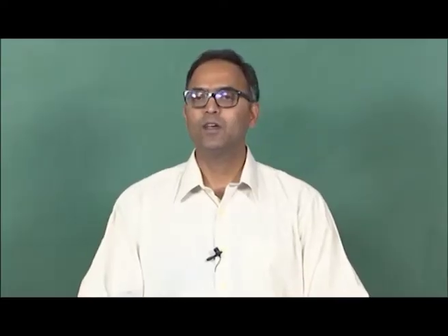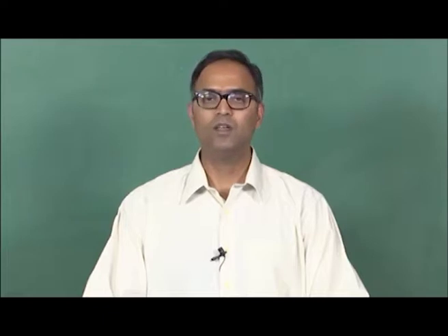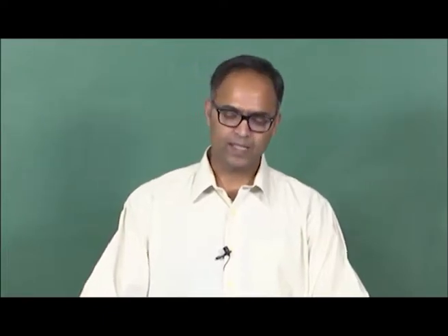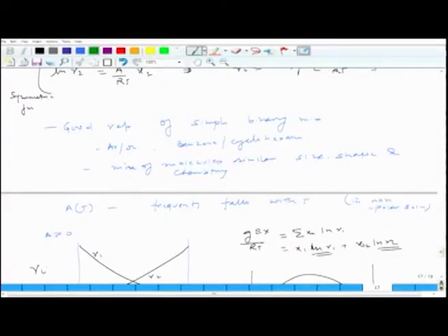Welcome back. In the last lecture, we introduced a simple equation, the one-constant Margules equation, which satisfies the boundary condition for g^E to be 0 when x approaches 0. We commented that such an equation works well for binary mixtures like argon-oxygen, benzene-cyclohexane.